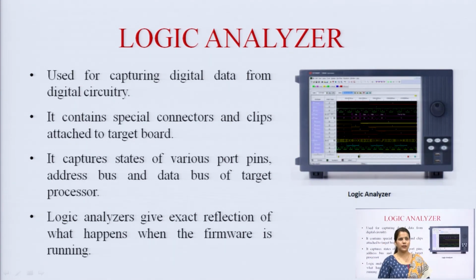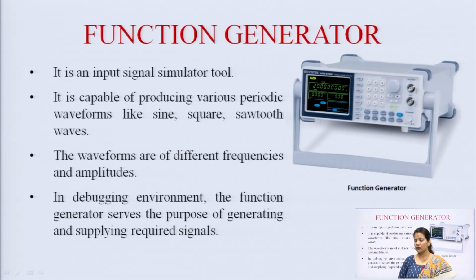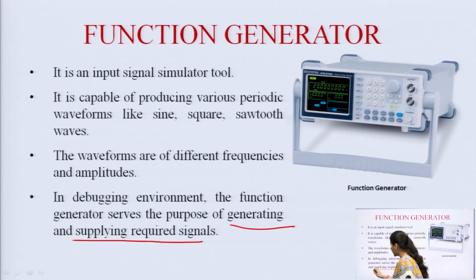Another one is the logic analyzer, it is used for capturing the digital data from the digital circuits, and that digital data is judged at different points to see if the signals are obtained properly. So, they give the exact reflection of what happens when the firmware is running. Function generator is another input signal simulator tool, and it is used to produce various periodic waveforms like sine, square, sawtooth waves, etc. In the debugging environment, the function generator serves the purpose of generating and supplying the required signals. So, this is the main purpose of this device.